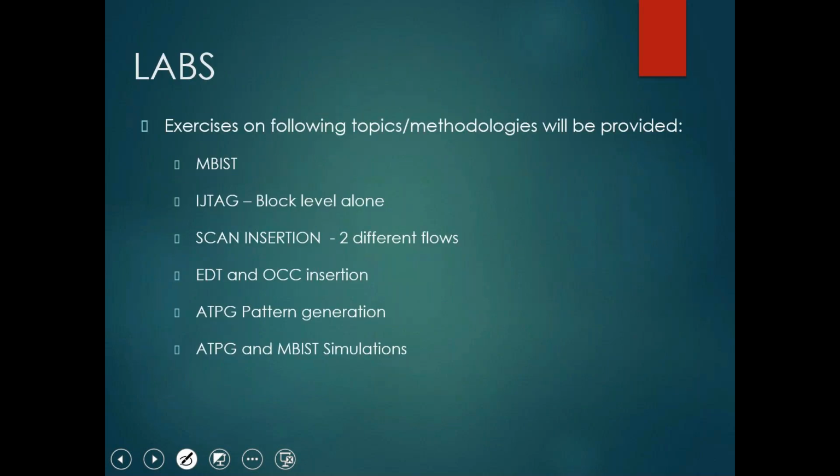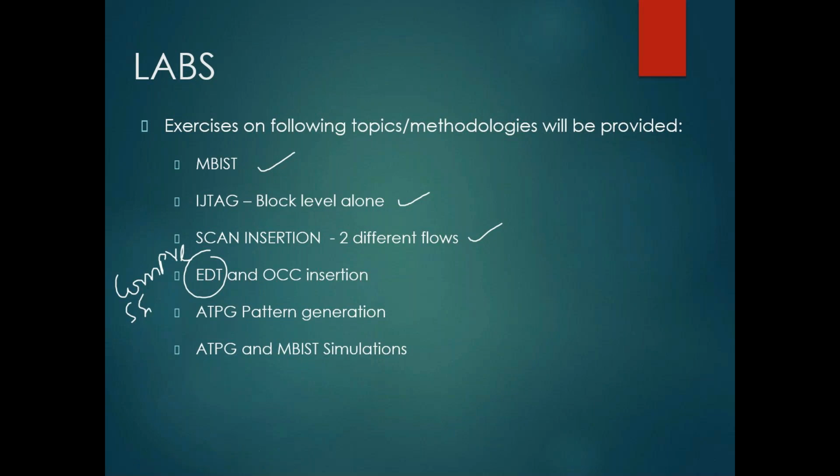So how are the lab sessions provided here? On the following topics, we are going to discuss the lab sessions, the practical sessions. Many of you may have a question: we are speaking more about the defects and the theoretical topics, how the DFT methodology works, then what about the practical sessions? So here we are going to cover the memory-based practical session, the JTAG block level insertion, the JTAG protocol which I told, and the scan insertion, two different flows I have. EDT stands for embedded deterministic test, which is nothing but the compression. And then we are going to see the OCC insertion.